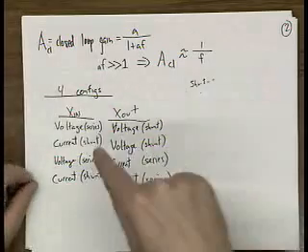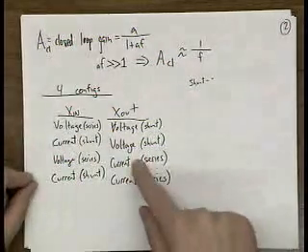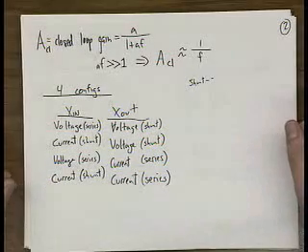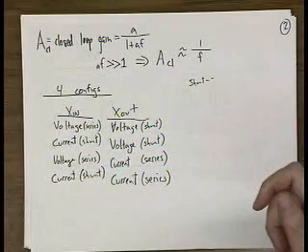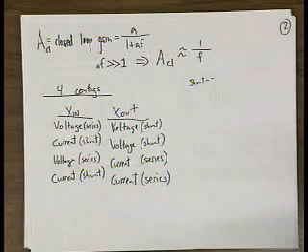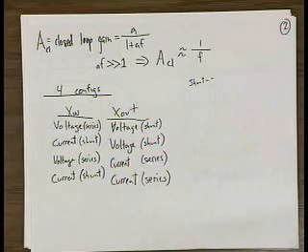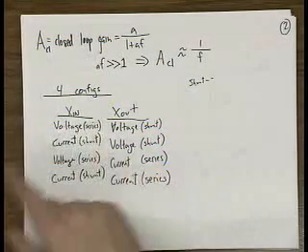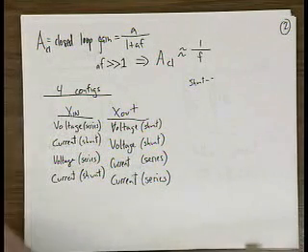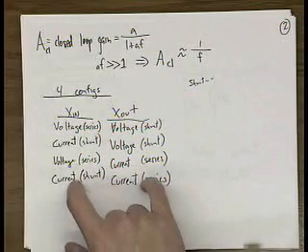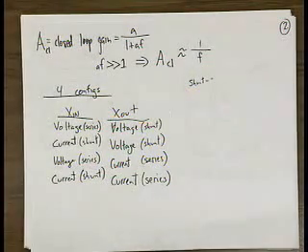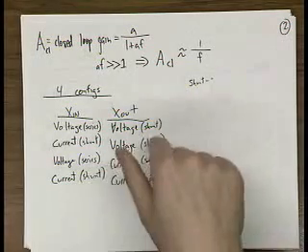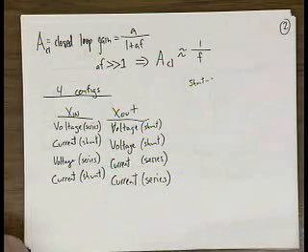So either memorize this table or keep it handy, because sometimes it's easier to figure out if you're sensing a voltage or current, and sometimes it's easier to figure out if something's in series or in shunt. You'll see that the relationship between voltage, current, and series shunt are inverted between input and output. So it gets tricky to keep track of, and I have to remind myself by going through this exercise every now and then exactly what kind of feedback it is.